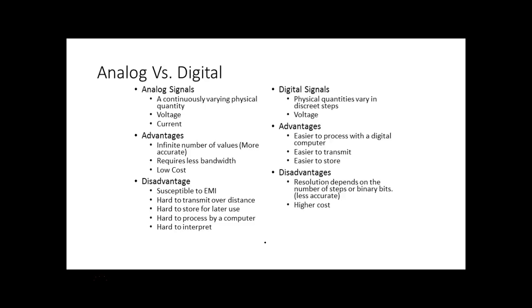So what we do in binary, the more bits we use to represent the analog value, the higher the resolution. If I'm using 4 bits, and I'm using voltage, I can only represent 15 voltage levels, because with 4 bits I get 16 combinations. But one of those combinations is 0, and 0 represents no voltage, right?